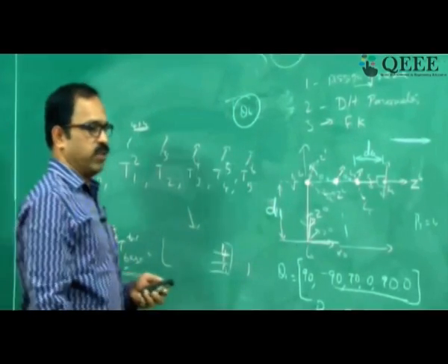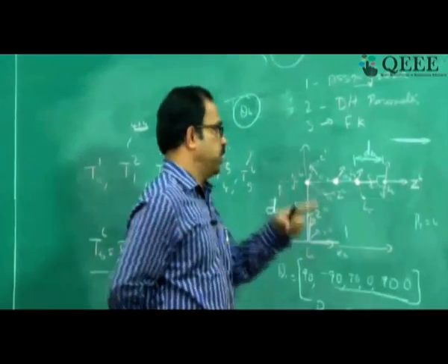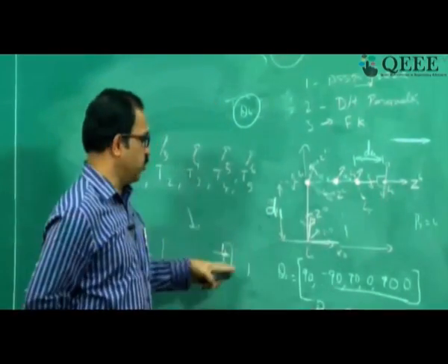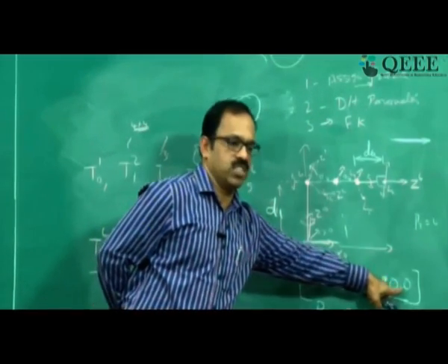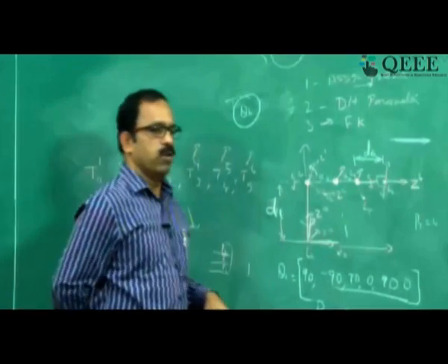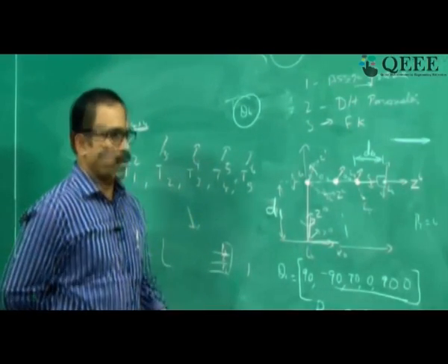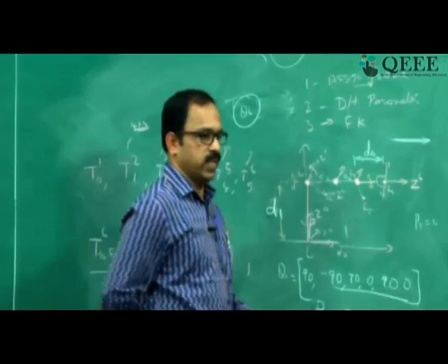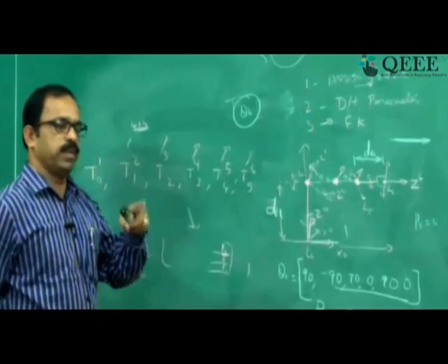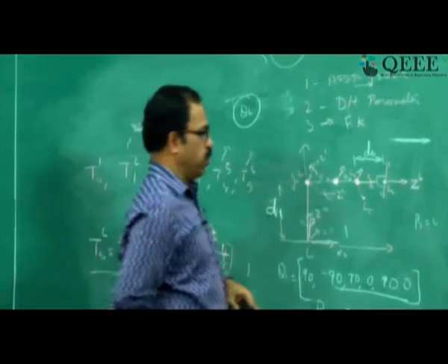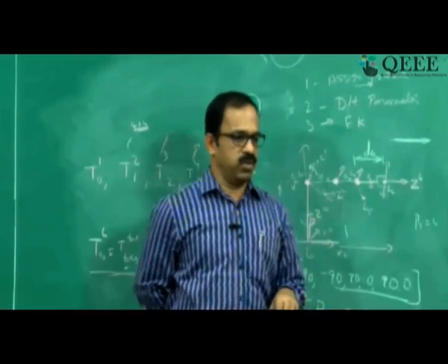Now as a partial check, if you substitute into this PQ relationship Px, Py, Pz the values of theta 1, theta 2, theta 3, theta 4, theta 5 and theta 6, you will get Px, Py, Pz. So for the tool to base relationship, you will see that Px is equal to A3 plus A4 plus D6, Py is equal to 0 and Pz is equal to D1.